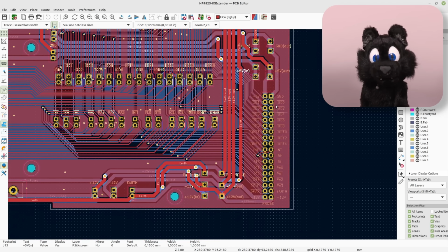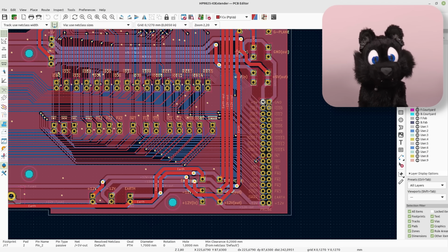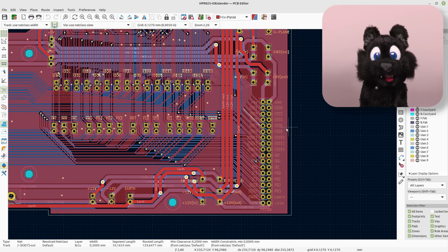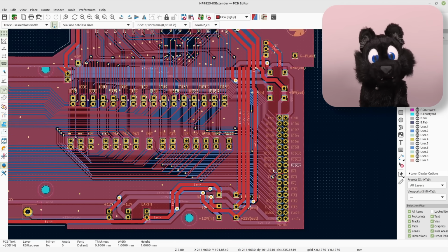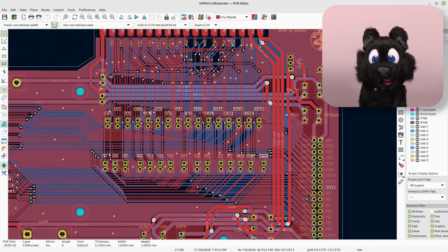The pin header fits nicely on the edge. I kept the same layout of pins as the bus connector for simplicity. Oh, and I also labeled all of the connections, so poking something with a logic probe should be less pin counting than normally. The data bus jumpers are one big block, and the control lines are grouped by topic: IRQ related items, addressing, reset, status, I/O control, and DMA.